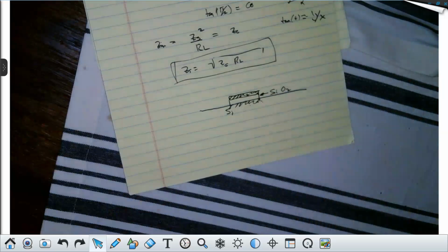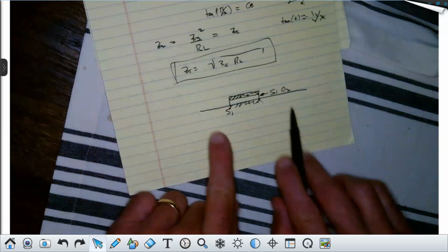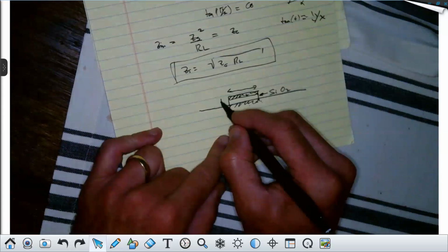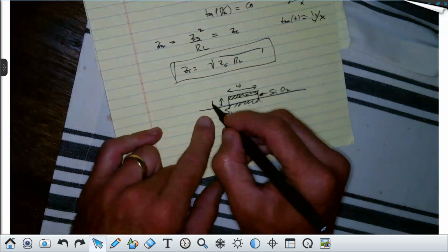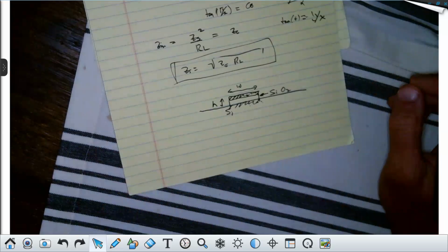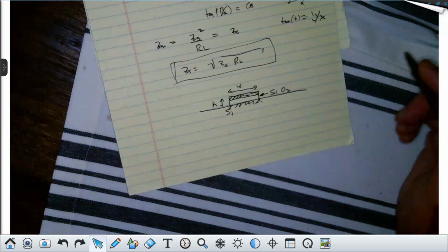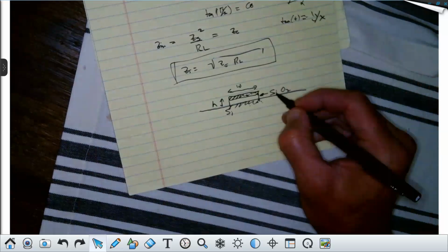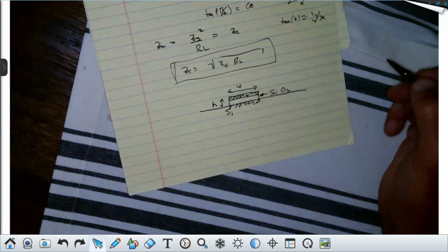And we can control the impedance of this transmission line by dictating the width and the height. I'm not going to ask you to get into this now. This comes later, but I want to tell you the way we actually deal with changing the impedance of a quarter wavelength line is by the ratio of width to height, and also the material. Silicon dioxide has a certain relative epsilon. That's just some information on how we're going to build these things.